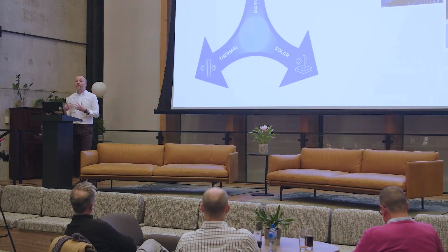The less glazing I have, the better my thermal performance, because I've less glass, but the poorer my daylighting, in simple terms. So I go the other way and I go loads of glazing. Now I've got much better daylighting, but I've got very high heat gains, casual gains or heat gains within those spaces that I have to cool. So therefore I'm using a lot of energy to cool. It's a difficult one to get right. How do we optimize, and how do we find that sweet spot, or that middle ground?